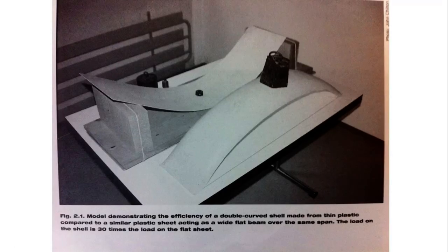And here's a model, I think this is from Isler's studio, just demonstrating this principle of bending, making the very slight bend in the structure. So it's the same sheet here. I think it's just a sheet of plastic. It's the same sheet, isn't it? Which is failing under a tiny load here. By just giving it that bend in that direction, that's a synclastic. It becomes a synclastic form.